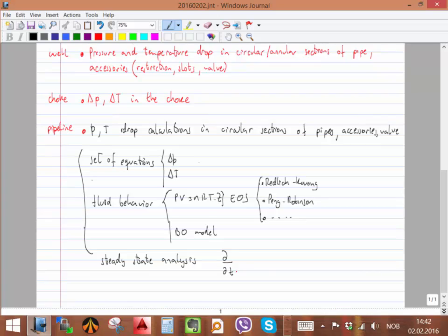Let's say that you have a graph that has choke opening, and you have here pressure upstream of the choke. Let's put it in yellow. So the choke opening initially was at a certain value. Let's say it was completely open at 1. Here I have 0. But then I change it and put it in another position very abruptly. Okay, closed 50%. So what's going to happen with the pressure upstream of the valve?